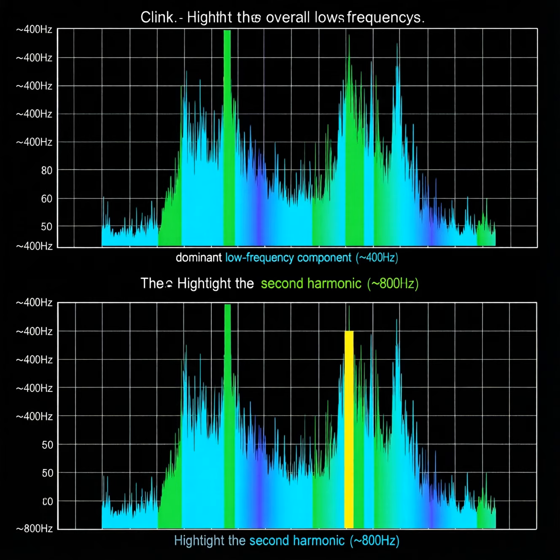The lower peak corresponds roughly to the fundamental frequency of the pot's first flexural mode, while the higher one is its second overtone. Because stainless steel has a high elastic modulus and low internal damping, these modes persist long enough to be clearly resolved in the spectrum. If we map each frequency to its nearest equal tempered musical note, 400 Hz aligns with roughly D4 and 800 Hz with A5. Thus the clink produces a short burst that sounds like two notes played simultaneously, a sonic fingerprint